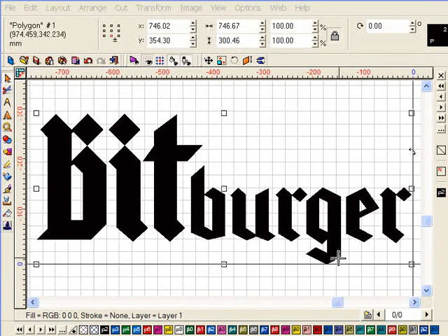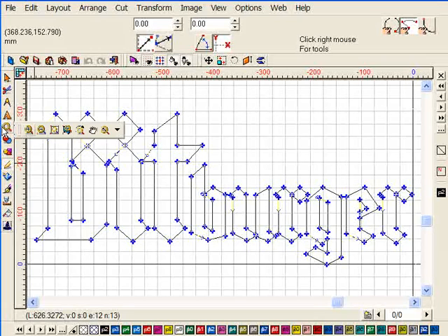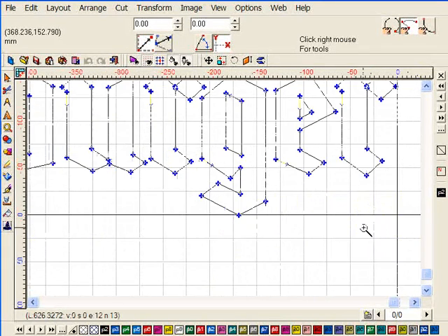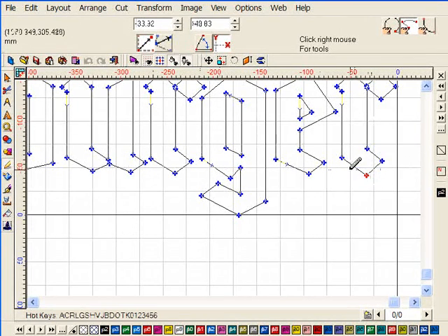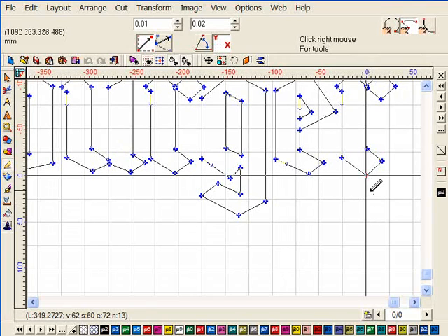It's done a pretty good job, but I have a few points to tidy up. I can achieve this more efficiently by using some of the keyboard shortcuts. All these base nodes of my object need aligning. I'm going to use a grid to help achieve this faster. First, I select this node and hit the L key on the keyboard. This will snap a grid line through this node and create a base reference point for the others to align to.